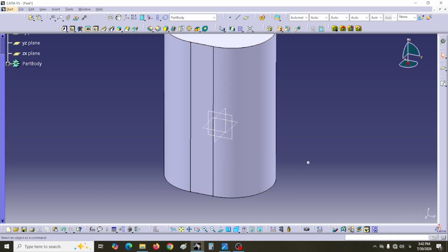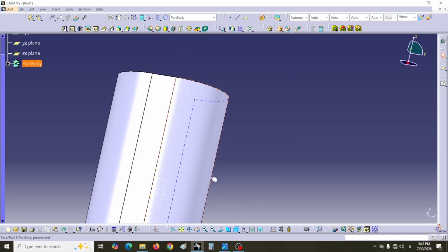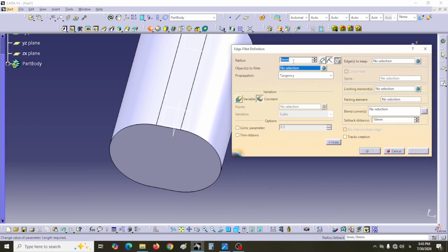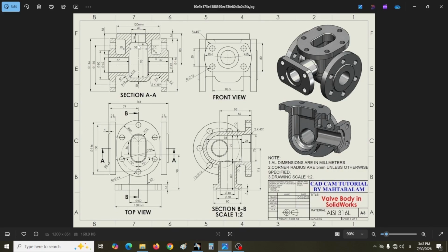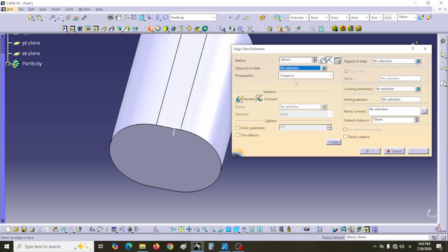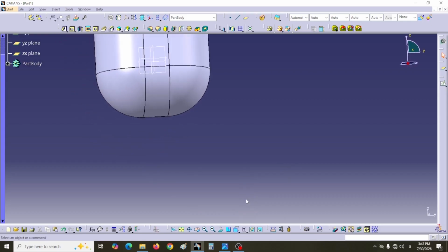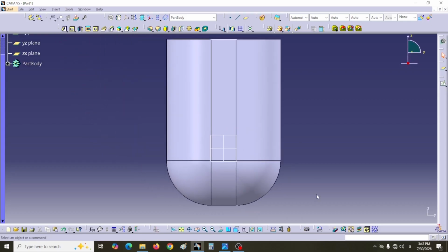The shape is finished. Look at the bottom of the shape. I need to make this part round. I will use the fillet tool first. I will set the fillet value to 36 millimeters. I look at the model from both sides and compare it with the drawing.